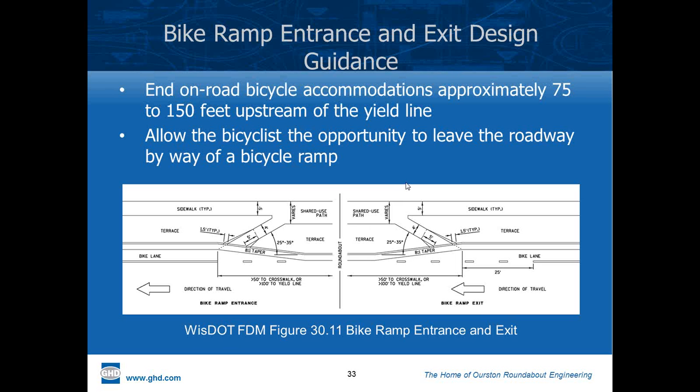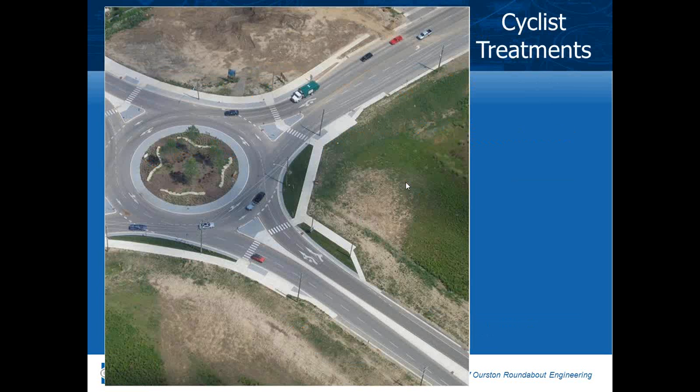So they can leave the roadway and use the bicycle ramp. So we don't ever provide separated bike lanes in roundabouts. We would never paint a bicycle lane into a roundabout. We would terminate the cycling lane and show the diversion point, go to the wider sidewalk, use a shared path in this case. The difficulty with this is, does the pedestrian continue, or does the cyclist continue with pedestrians as a pedestrian, or do they stay mounted on the bicycle and interfere with pedestrian activity?